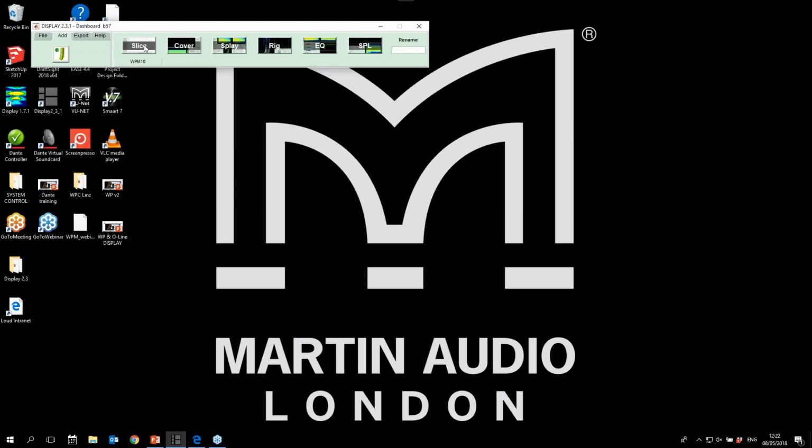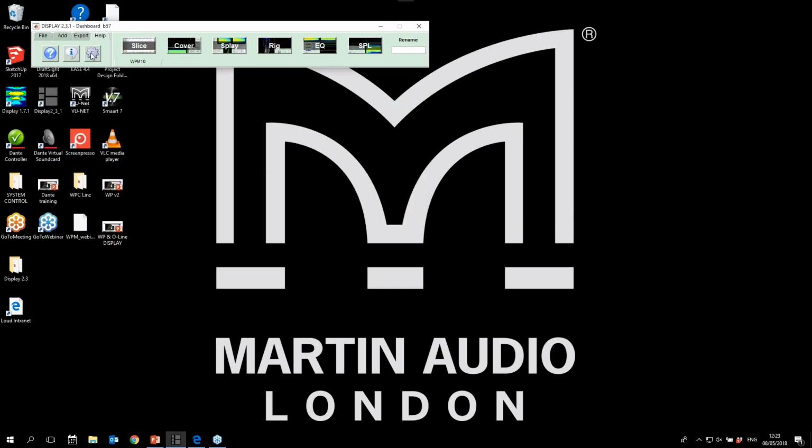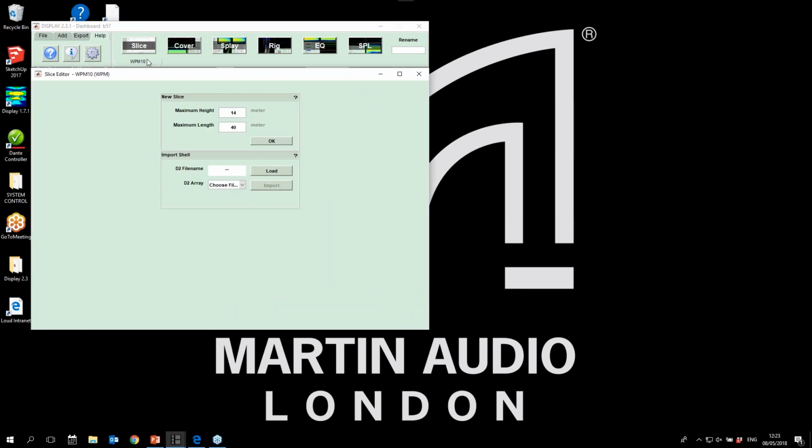Then we can move on to our slice. Oh, at the minute we're displaying this in feet. It's because I'm currently working on a project in America, and they are still using imperial measurements. I'll just quickly change that. I'll show you how to do that. If we click on Help, click on the preference edit and check the metric box. And when we click back on the slice, it's changed to meters.